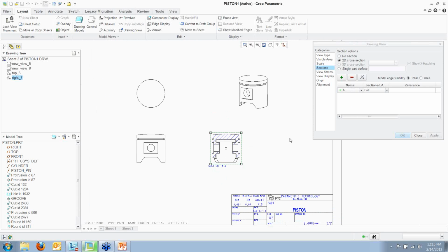Now, a lot of times we get simple questions, though I try not to make these completely basic, so this isn't going to be straight out of the intro class or the detailing class. We have two methods for putting arrows on. I found a lot of people don't know this. One method is to just scroll to the right, pick where it says Arrow Display, and select which view I want the arrows to be on. And it puts arrows on that view.